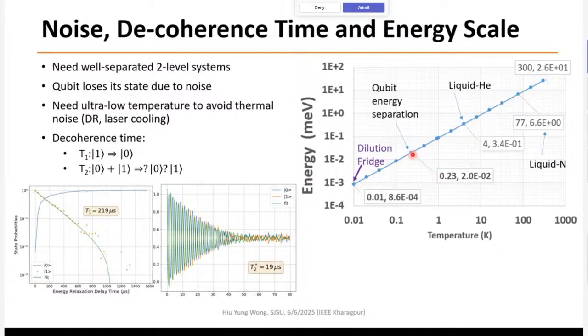It corresponds to about 200 millikelvin of thermal energy. Why do we do that? Because this corresponds to a frequency, h bar omega, of about 5 to 10 gigahertz. And that is what we can do well in electrical engineering, isn't that? We can do microwave very well at 10 gigahertz or other modulation, right? So this is the level of the qubit separation.